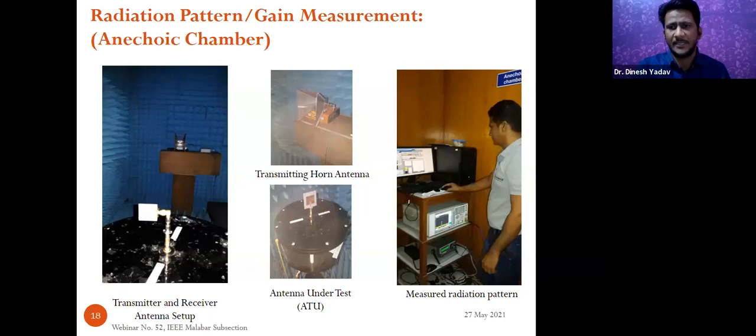The very crucial thing in the reconfigurable antenna is how we are supplying or feeding the energy to the antenna, and the energy which we are feeding to the diodes which we are additionally using in the antenna is also very crucial. Because if you are using wires, diodes, inductors and capacitors with your structure, then it becomes more bulky. And if we check the radiation characteristics, sometimes these components interfere with the other bands. The resonance may shift from the operating point you are expecting during simulation, and in measurement you do not get the right results. So these are the challenges we have to look after during our design, and we need to focus on how to minimize these effects.